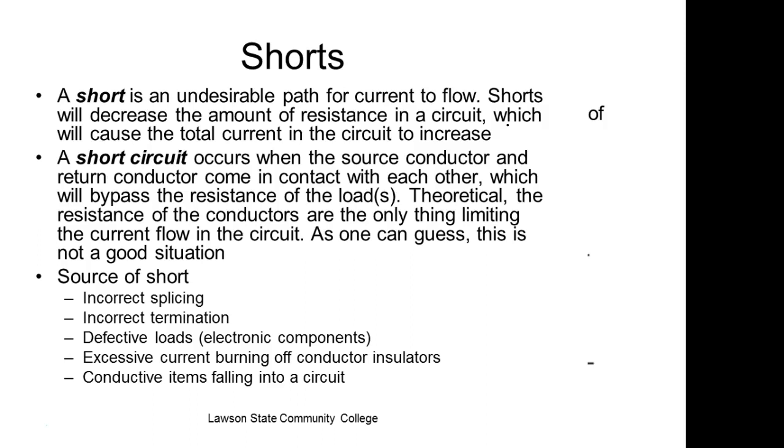So NEC rated a 14 gauge wire at 15 amps. So a 14 gauge wire would run on a 15 amp breaker. Right? Sources of shorts: incorrect splicing, incorrect termination, defective load, and also chafing.